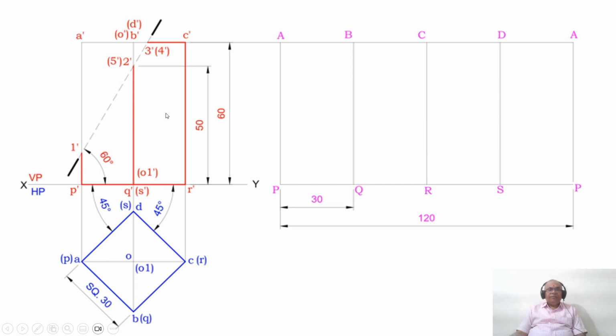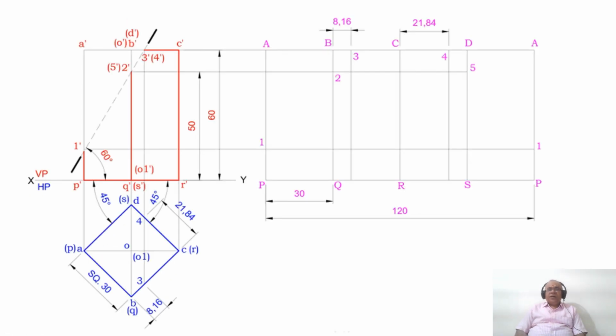So this is how you name the sectional points by considering the developed portion of the surface. Once you do the naming of the sectional points, then I need to transfer them to the development. First, A dash B dash is in true length? Yes. And AP is also in true length?